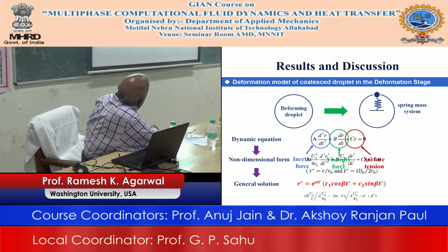in Fluent. Okay, so then this becomes a dynamic equation for a deforming droplet. So this is the inertia force, this is the viscosity, that is like a dashpot, and this is like the kx, which is the surface tension. So all three physical effects become a part of this spring dashpot system.